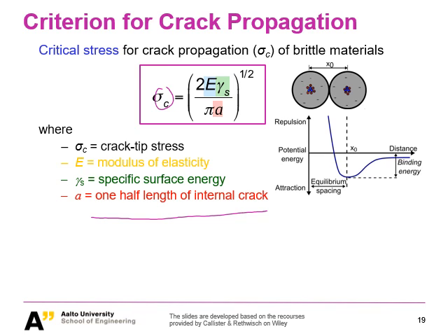That's a crack, right? That's our fracture. So that's why if we just want to create a crack, we're creating new surfaces, and deep down we're trying to separate the bond, and we're trying to overcome this kind of binding energy between the atoms. And in the end, you will develop your fracture. So this gamma S is highly correlated to the binding energy over there. I hope you get the sense of it.